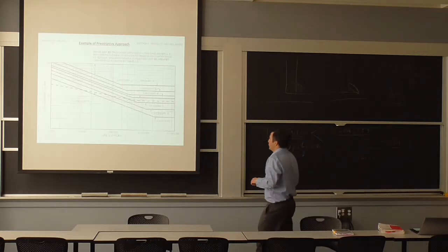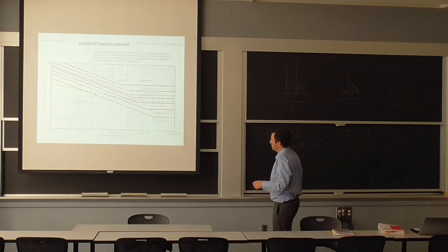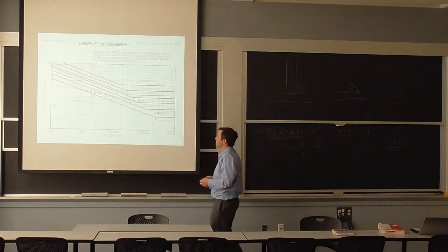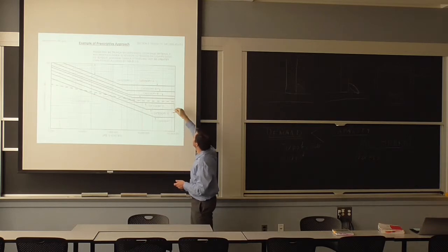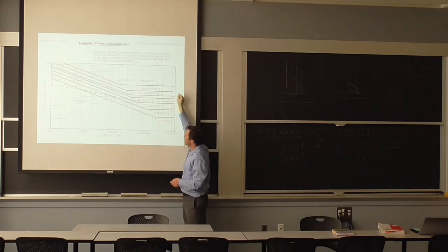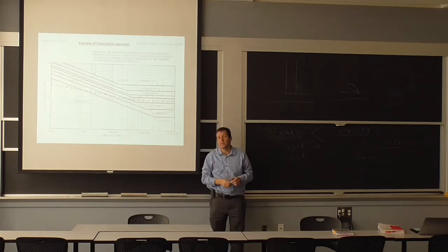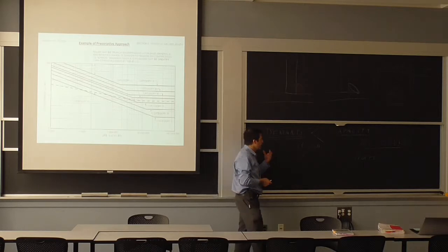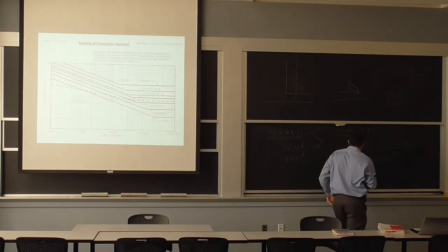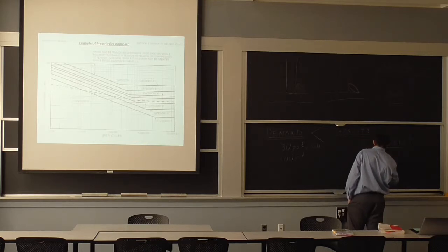So when we're talking about the capacity here, it becomes a question of demand as well for the number of cycles. What is most important here in terms of the process is if you have welding, even for vibration, you're going from something that would resist more than 20 KSI to something that is more of the order of 2 to 3 KSI. And that's the factor of 10 that I mentioned at the very first lecture. And so when you think about the capacity here, I would include joining in your mind. Does it change the whole perspective?